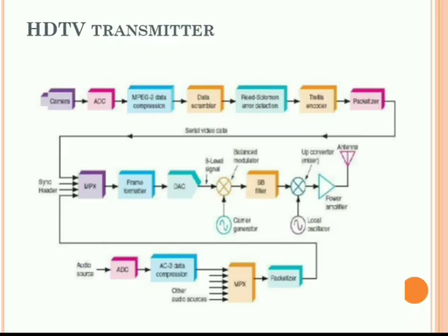Okay, after this encoder, the video and audio data streams are packetized, that is, passed through the packetizer, where they are converted to short blocks of data bytes that segment the video and audio signals. Okay, these packets are then multiplexed along with some synchronizing signal for the formation of the signal to be transmitted. The result is a 188-byte packet containing both video and audio data plus 4 bytes of synchronization bytes and the header.